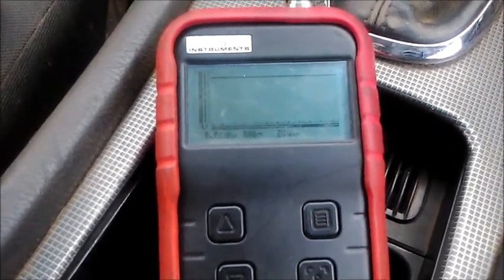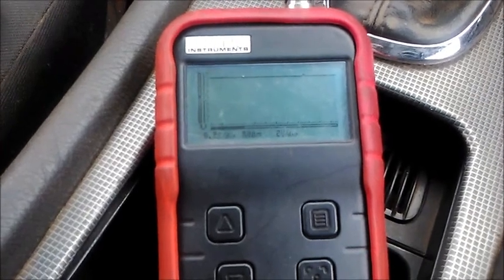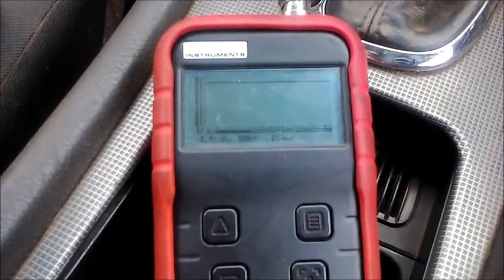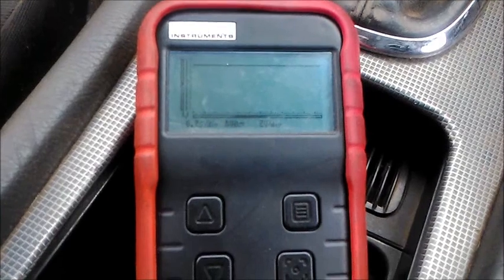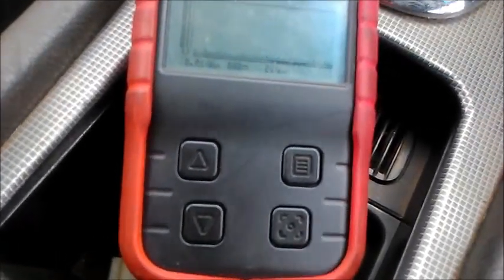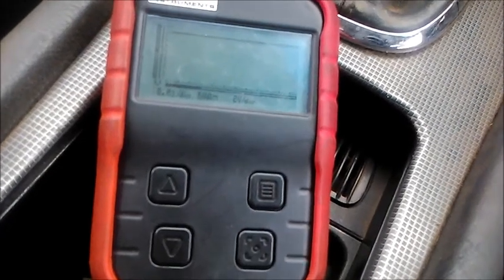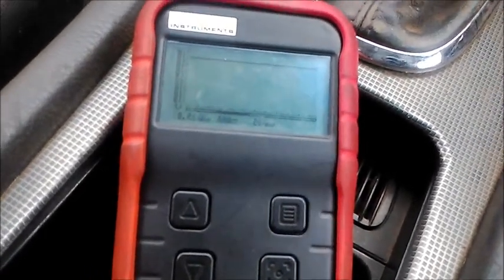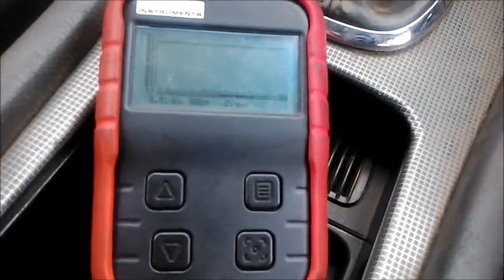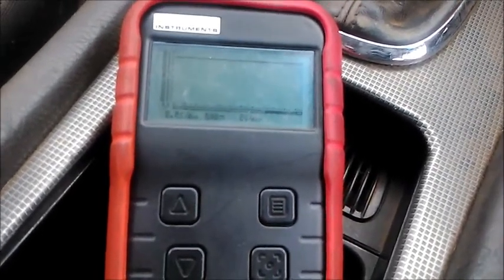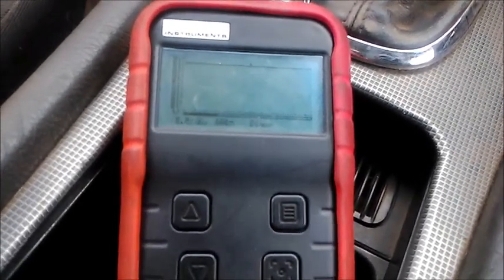This is a well and truly dead speed sensor, in the valve body on the transmission, at the bottom of the transmission. It corresponds with the data I saw, so right there is our problem.